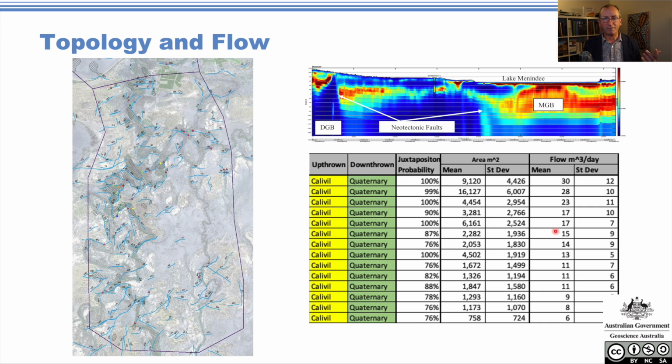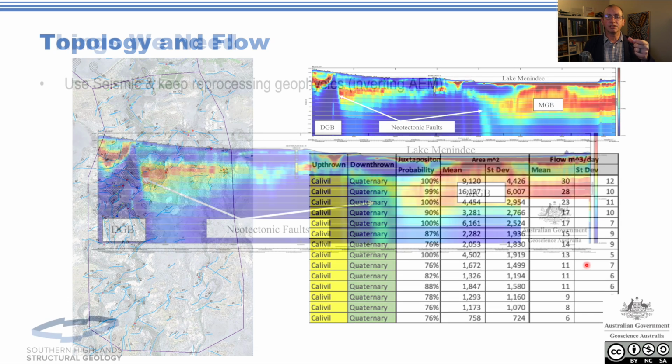So you can get a P10, P50, P90 flow across the day, per day. So how these were used, Phil Hayes, who's now at UQ, was at Jacobs at the time, was doing the modelling. He took these flow units and modified the Blanchetown clay's hydraulic conductivity at where these faults were to go through and say, well, look, here's my distribution of flow I can see across these cells.